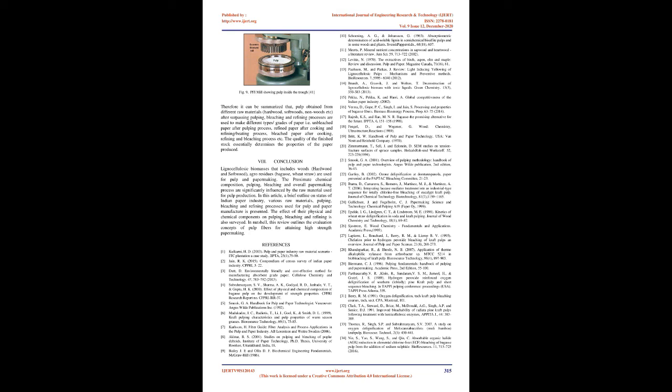The distinguishing factor between the two processes is the use of chlorine dioxide, which is used in ECF but not in TCF. With the replacement of elemental chlorine, Cl2, by chlorine dioxide, ClO2, in bleaching sequences, the pulp and paper industry has reduced considerably the formation and discharge of chlorinated organic material into the aquatic environment.